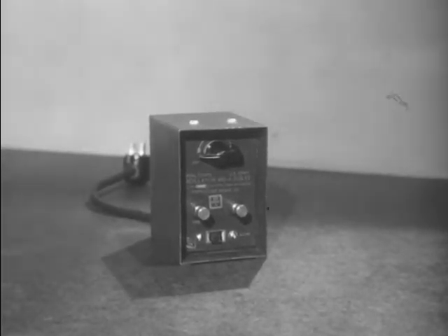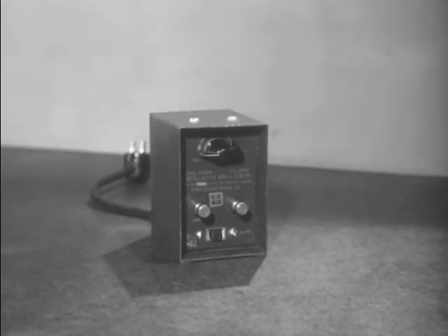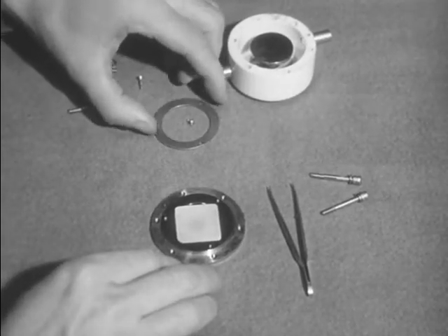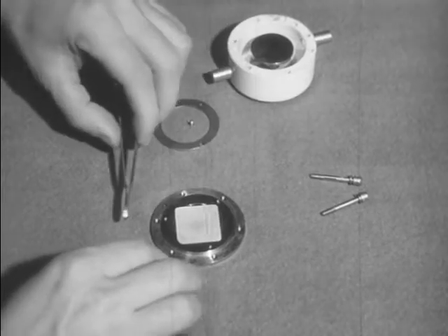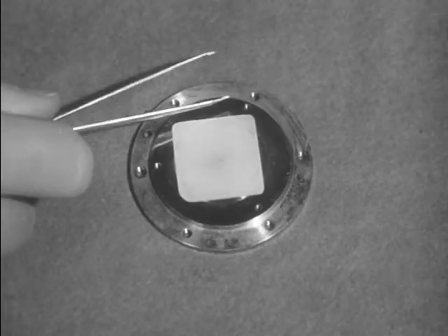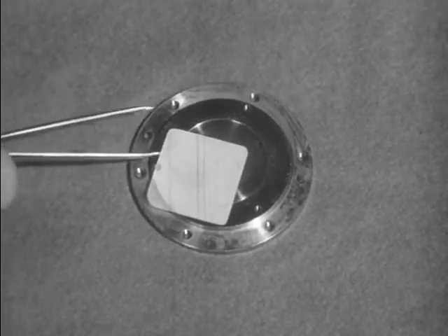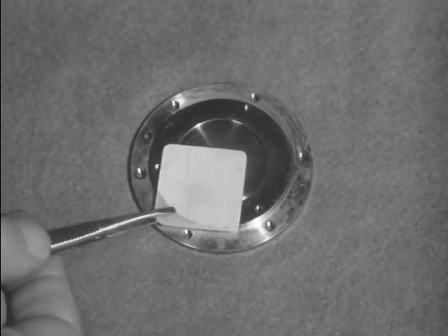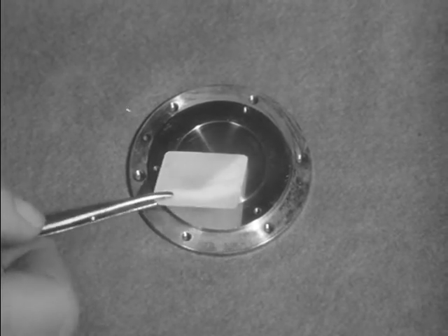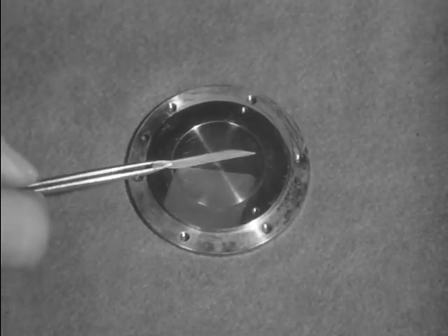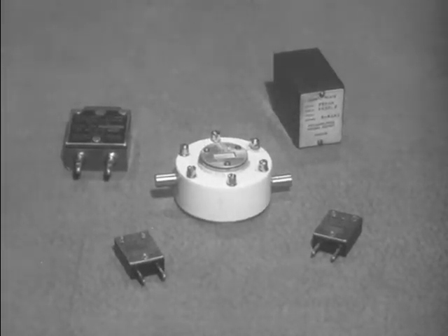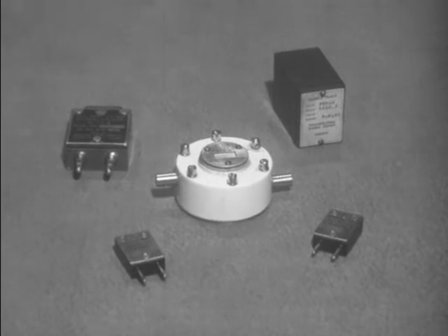Another oscillator is the crystal-controlled type, designed to operate on one or more specific frequencies and is not variable. The important thing in the crystal-controlled oscillator is quartz. Quartz, when cut and ground to accurate dimensions and placed in an electrical field, will vibrate at a particular frequency determined by its physical dimensions. The mounted crystal for the indicated frequency looks like this.